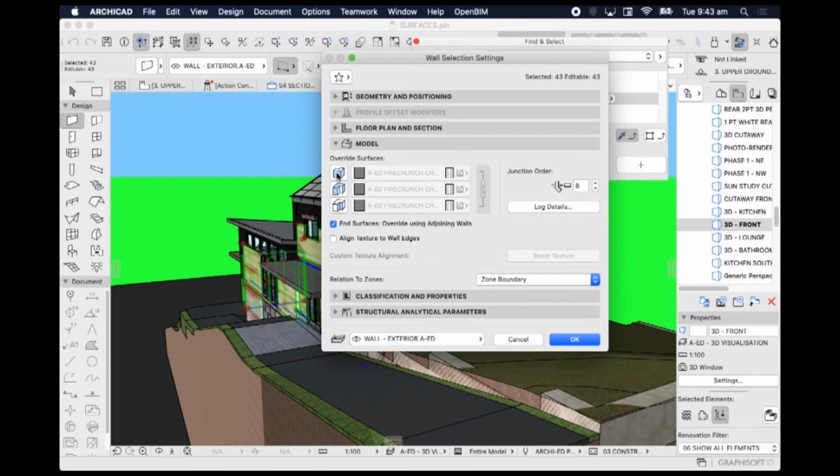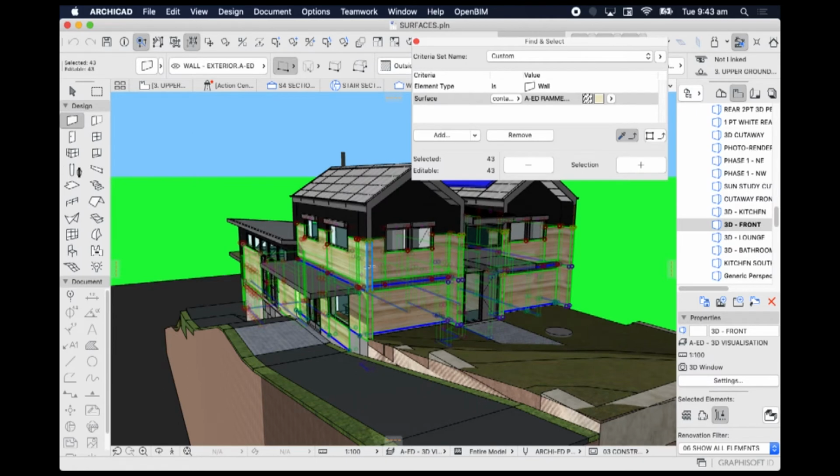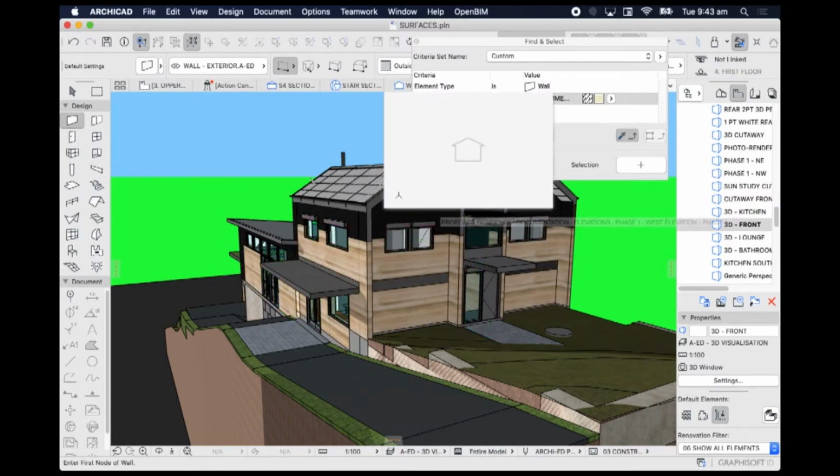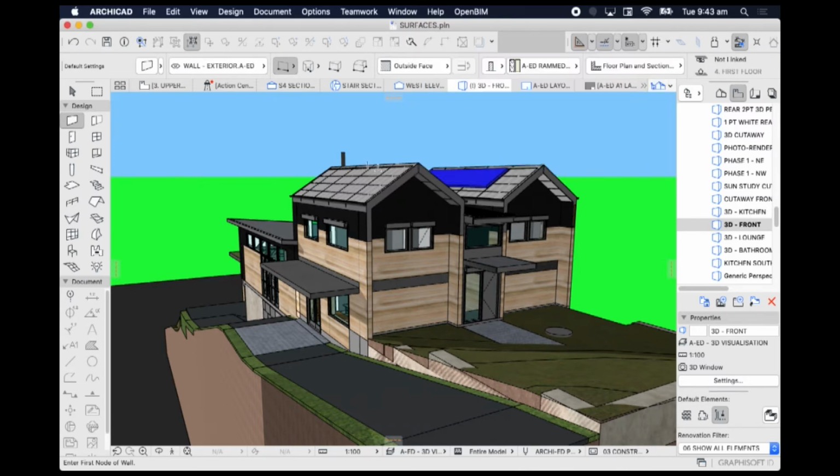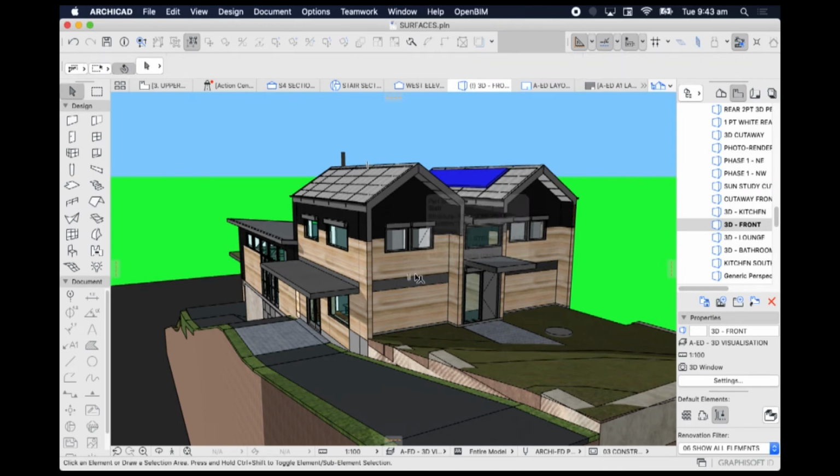And in walls, we have three different parts: an inside face, an outside face, and an edge face. When we look at columns, or beams, or slabs, or roofs, we have different ways of differentiating the surfaces of sides or parts of those objects. So this allows us to select, refine, or redefine the way that we do our views.